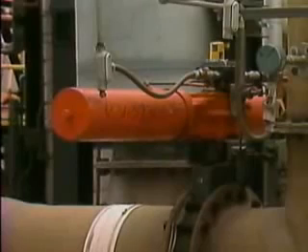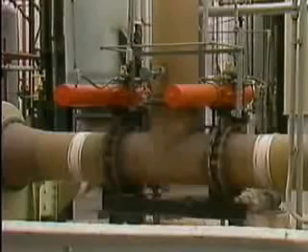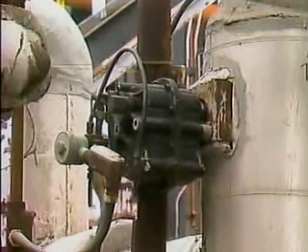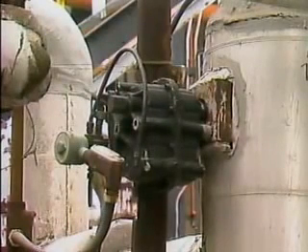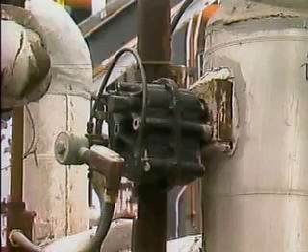This piston actuator is a pneumatic operator that uses a piston inside an airtight cylinder to position a valve. It's generally more suitable than a diaphragm actuator for jobs that require relatively long stem travel or more force to position a valve. This vane actuator is a pneumatic operator that uses air pressure against a vane or paddle to position a valve. This type of pneumatic operator is used primarily with ball, plug, and butterfly valves.